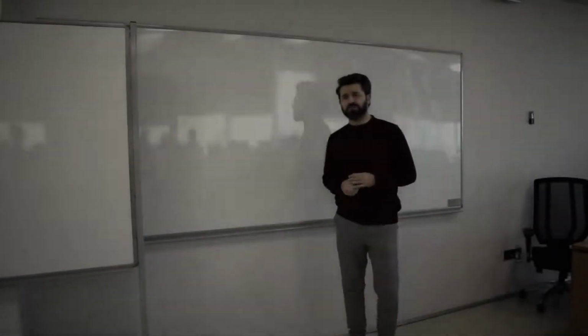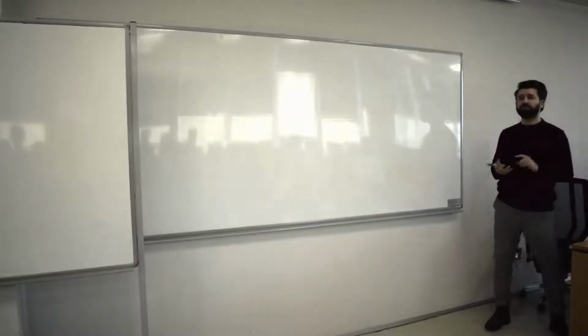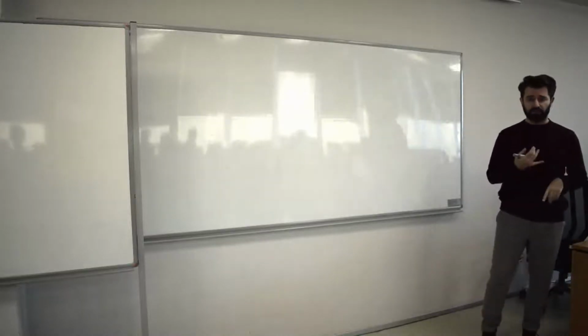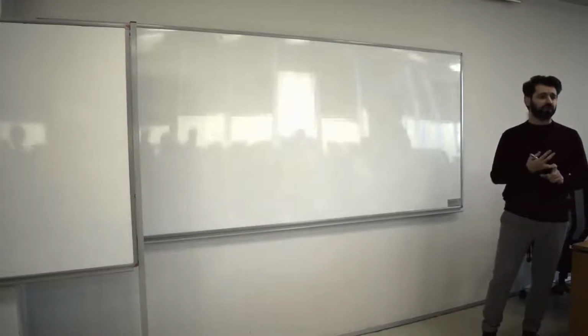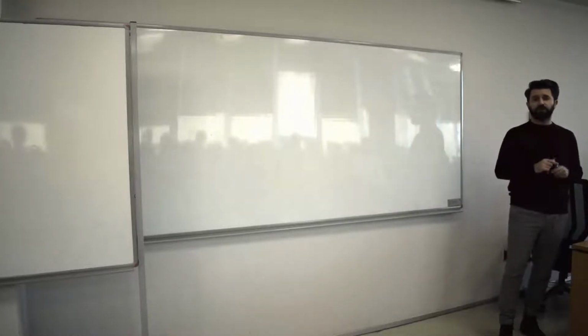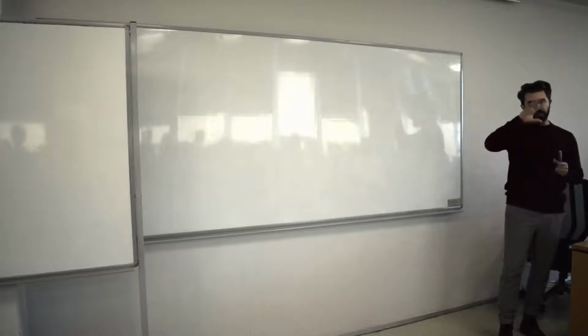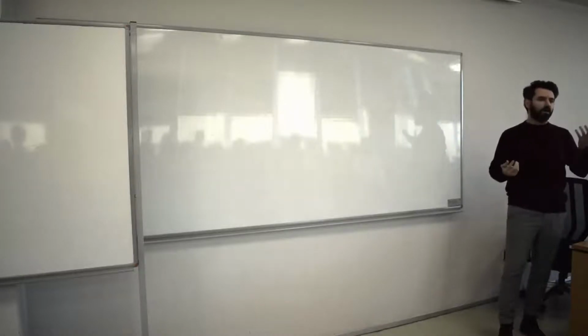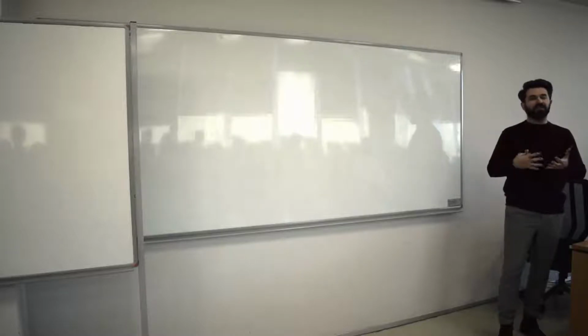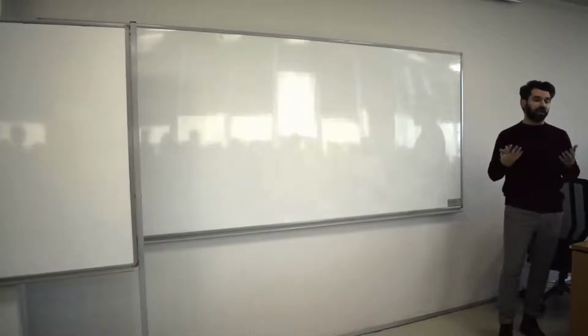Today's lecture is going to be short because we already have covered registers and counters so far, as you know. We looked into synchronous and asynchronous counters, and one of the asynchronous counter examples was the ripple counter, right? The T flip-flops are connected to each other, and only one flip-flop is connected to the clock signal, and the rest of the flip-flops are connected to the outputs of the previous T flip-flop. So there is a cascade of these T flip-flops. They are triggered at different times, but that's good because that creates the counting functionality.